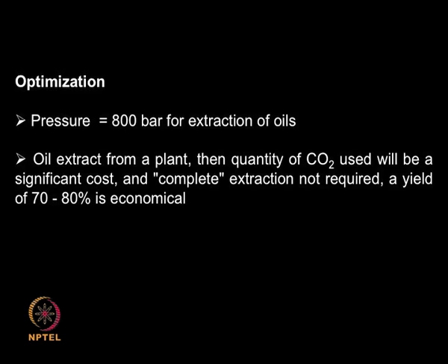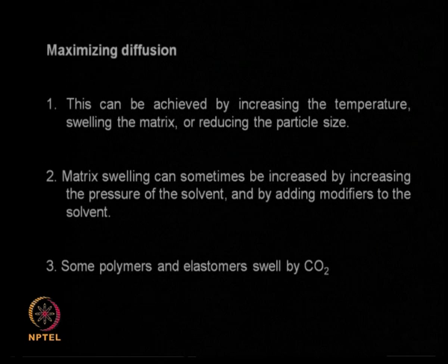because if you take an oil extraction plant, the quantity of CO2 used will be a significant cost, and complete extraction might not be required. Even a yield of 70 to 80% is economical, and most of the cost is because of the quantity of CO2 that is used actually.